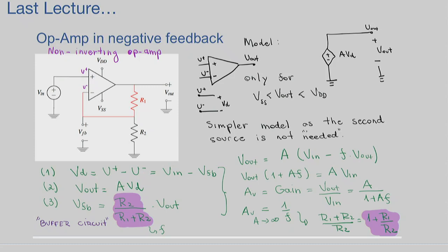The rails are the set voltage sources that we add to the operational amplifier such that we don't get an output of 100,000 volts, because we know that the gain of the amplifier, at least an ideal amplifier, is infinite, really, really large. Then, next in our design, we said, okay, let's change this operational amplifier to try to control the gain.